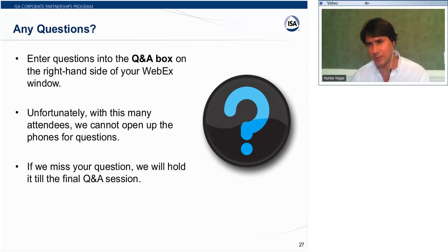Absolutely, yes. Especially in a steam drum, you can use radar. You can use capacitance, but it has issues. I would be a little leery of capacitance because the conductivity of the water is extremely low, and a capacitance transmitter is very affected by that conductivity. And so if there's very little there to begin with, then just a slight amount of change can make the reading change. Radar is going to be more consistent.